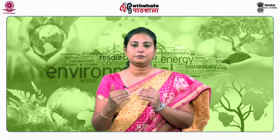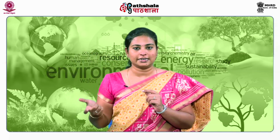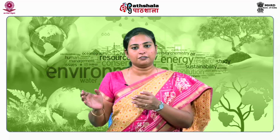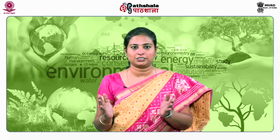You allow a retention period, you allow the solid material to settle down, and the supernatant will be decanted, which is carried out in the next phase. After decantation, it is the idle phase, you leave it idle for some time and then again the process continues. So, everything occurs in a single unit, that is the sequencing batch reactor.